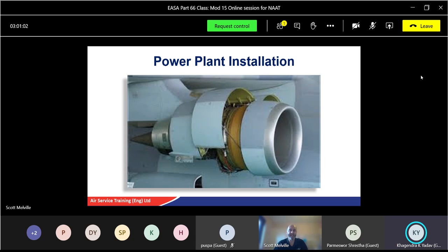Well, definitely thermal shock. P3, yeah, because they're already roughly about 500, 600 degrees. Good. Yeah, P1 would cool it down a bit too quick, and it will cause that thermal shock. Yeah, that's it. Okay.